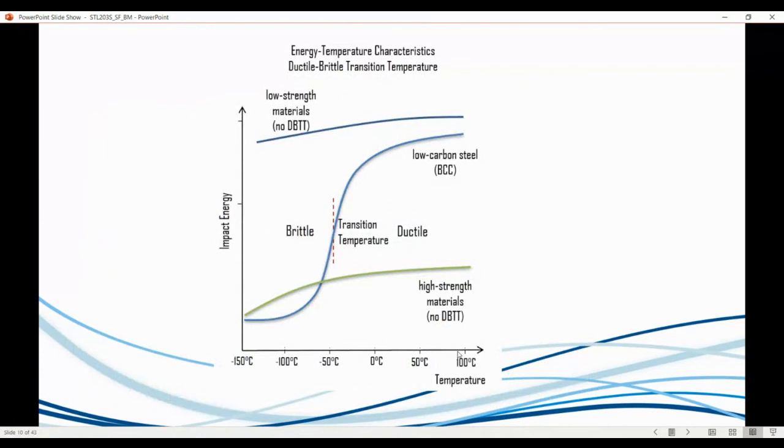So when I'm talking about the ductile to brittle transition, a normal low carbon steel, which is a normal mild steel as you guys know it, as you can see, as the temperature decreases, your impact energy becomes less. And what it means is that if it basically knocks into something, the steel will just snap. I mean, literally, it'll fail 90 degrees to the load or whatever. It'll be clean. It's a brittle failure.